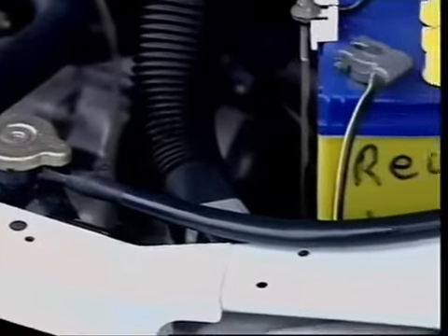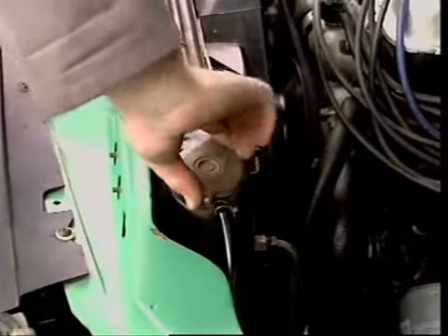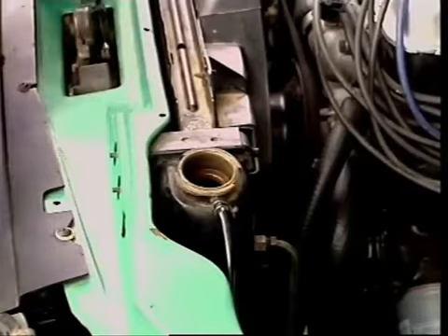A recovery system maintains coolant in the system at all times. As engine temperature rises, coolant expands. Pressure builds against a valve in the radiator cap until, at a preset pressure, the valve opens. Hot coolant flows out into an overflow container. As the engine cools, coolant contracts and pressure in the radiator drops. Atmospheric pressure in the overflow container opens a second valve, and overflow coolant flows back into the radiator. No coolant is lost and excess air is kept out of the system. Like water, air contains oxygen, which reacts with metals to form corrosion.